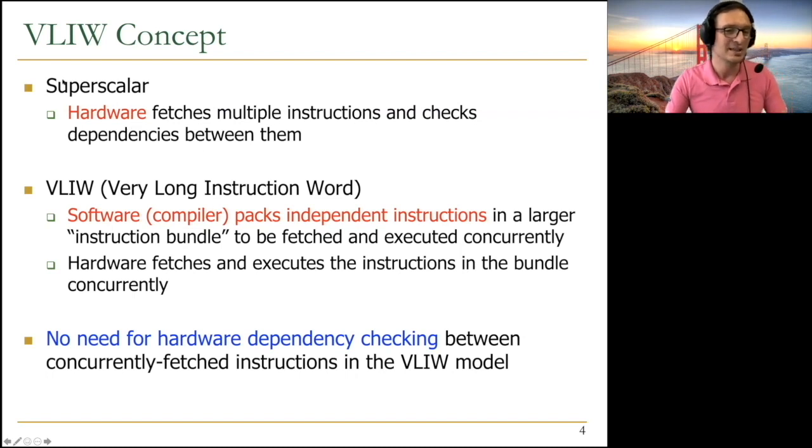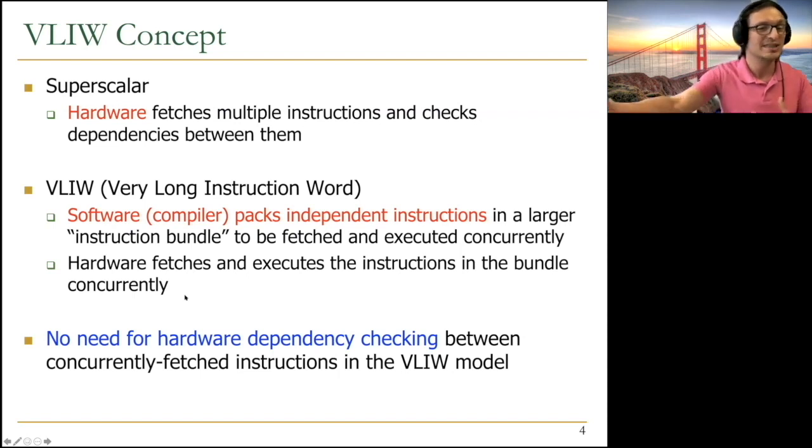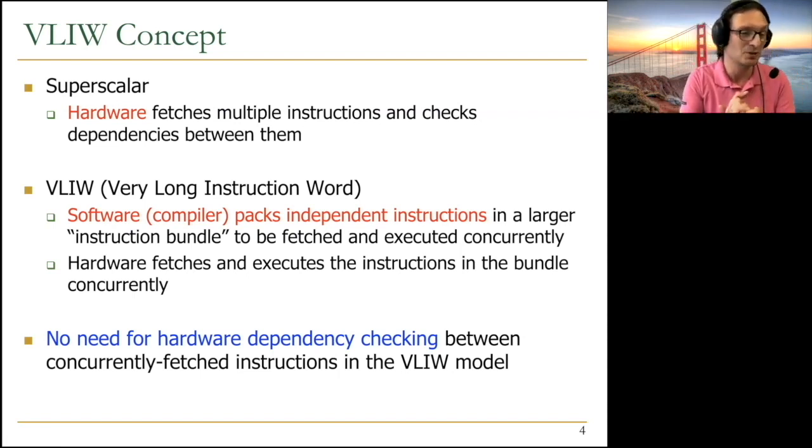And after learning superscalar, VLIW is not a huge step in a conceptual manner, of course, but the thinking is very different. And because the principle is that software needs to do all the dependence checking and ensuring that the instructions can be concurrently executed, now the software needs to be very intelligent.